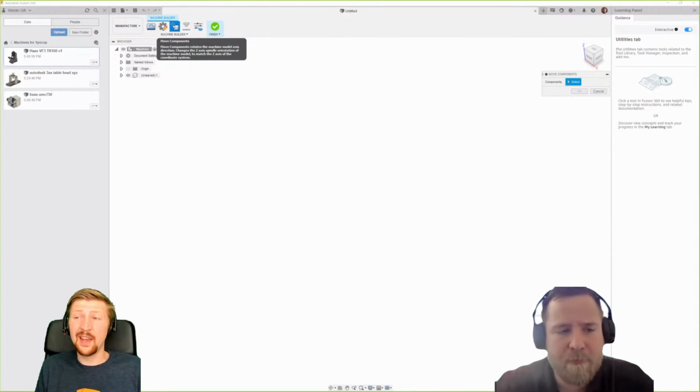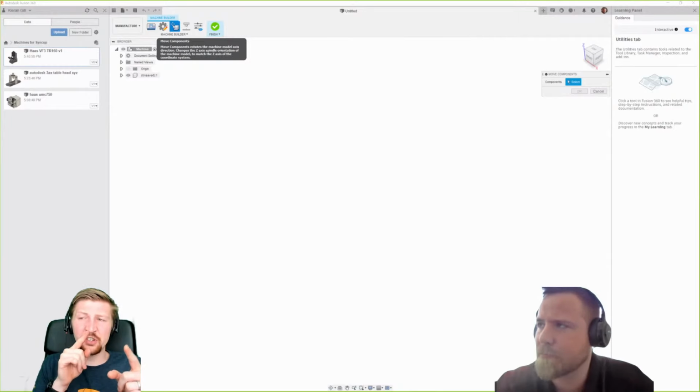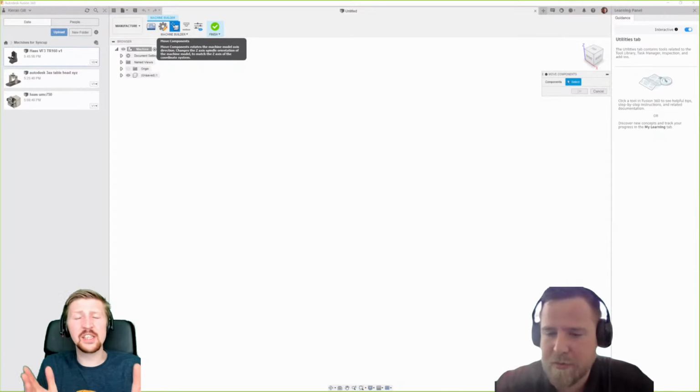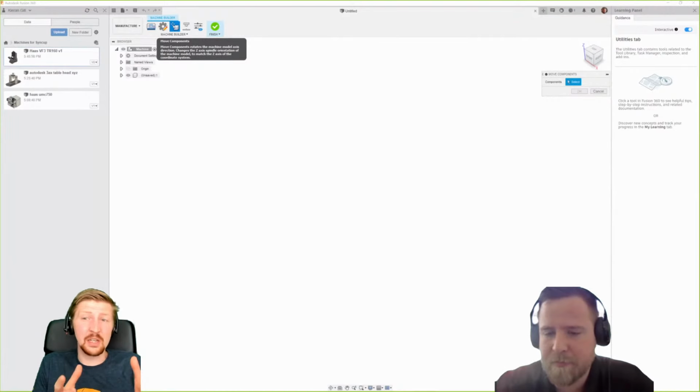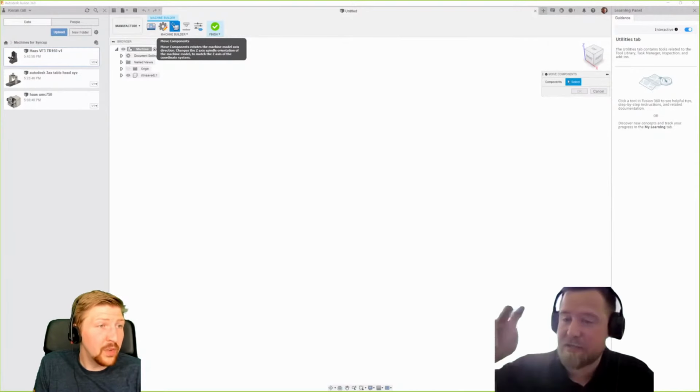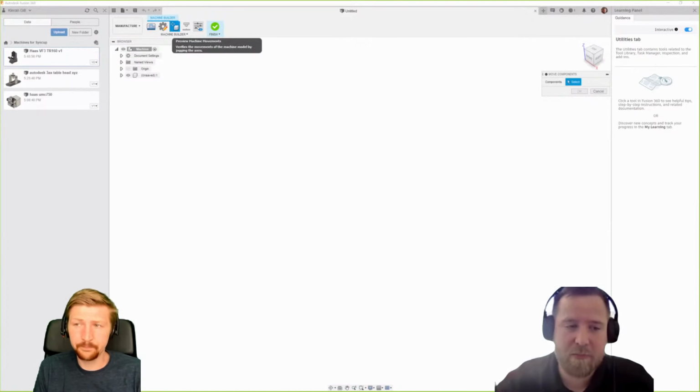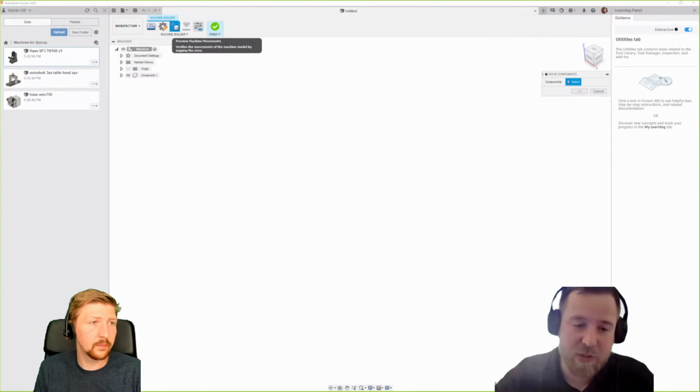So all you'd have to do is go in your kinematics file, probably change the chain, because now your Y is dependent on your X rather than whichever way it needs to be, and when you select the components, make sure you select it. All that's happened there is the default file we provided maybe doesn't quite show what your machine is, but hopefully Kieran has shown you the tools and how to use those and make that fit. Play around with the kinematics, click on OK, go to the jogging button and jog them, see what happens. That way you never have to leave the machine builder. You can always stay in the machine builder, play around, tweak, and then when you're good to go, you can hit the save button.